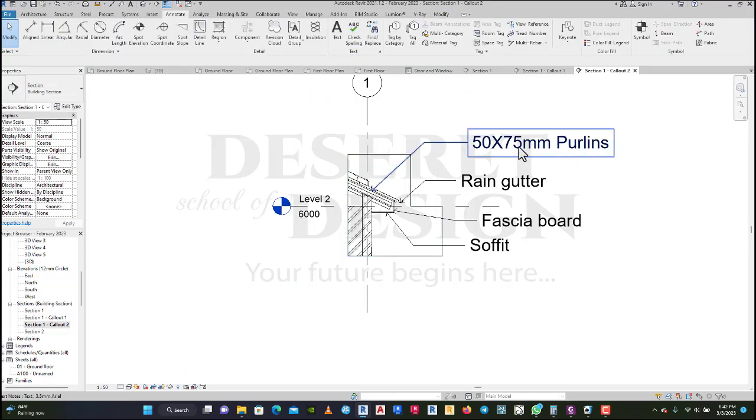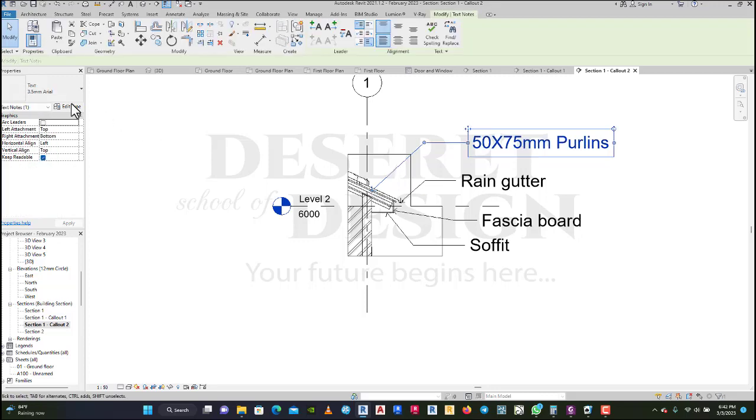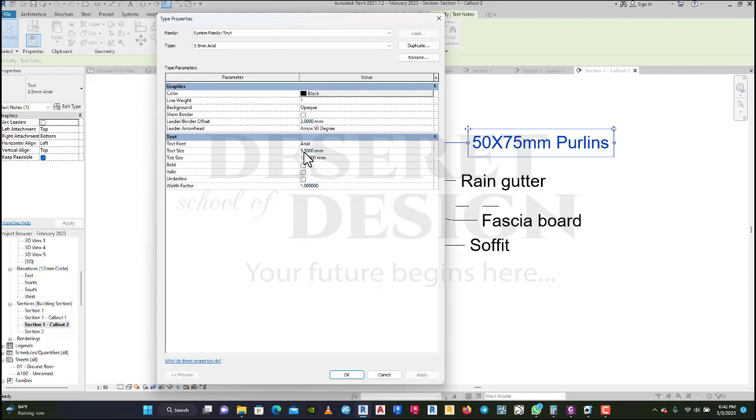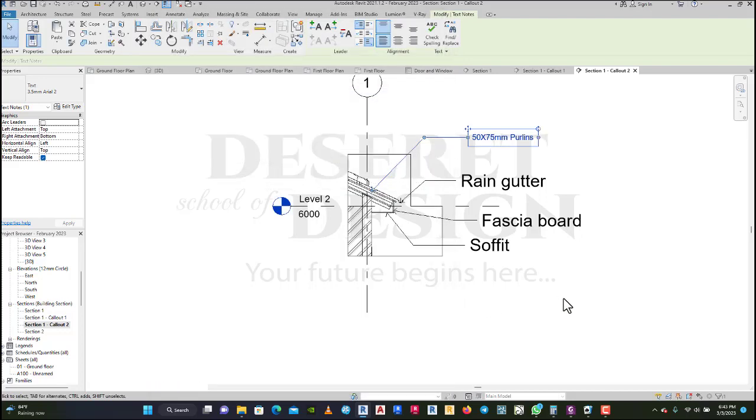It means that maybe my text is too big. Okay, it's too big. So I can select it, then edit it. Go to the edit type. Then maybe I'll use a different text. Now this text is used somewhere else. If I change it, when we do the dot tag, it's still using the same thing. It has changed here. But if I don't want to have a problem, I want this one to also be different. That means I'll do a duplicate. Okay. Then I can now change its parameters over here.